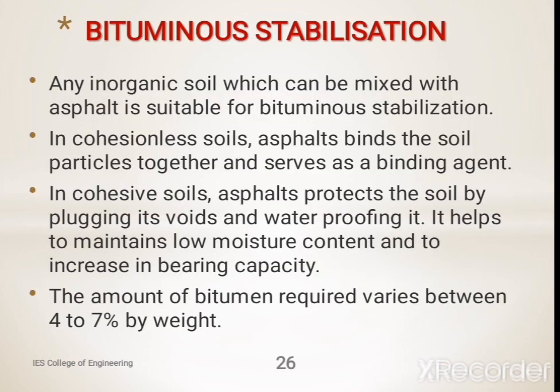The next type of stabilization is bituminous stabilization. Any inorganic soil which can be mixed with asphalt is suitable for bituminous stabilization. In cohesionless soil, asphalt binds the soil particles together and serves as a binding agent. But in cohesive soil, asphalt protects the soil by plugging its voids and waterproofing it. It helps to maintain low moisture content and to increase bearing capacity. The amount of bitumen required varies between 4 to 7% by weight.